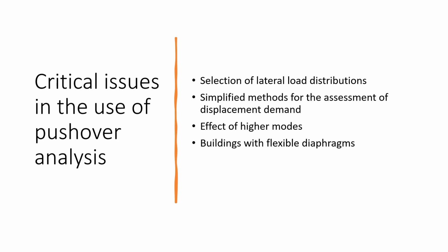Another aspect is the static approach. We use a nonlinear static approach, which allows us to compute a capacity curve, which provides the evolution of lateral strength as the displacement of a control point is increasing. This is a significant advancement with respect to the linear approach. We directly deal with displacements, which are definitely a better proxy of damage with respect to other measures.